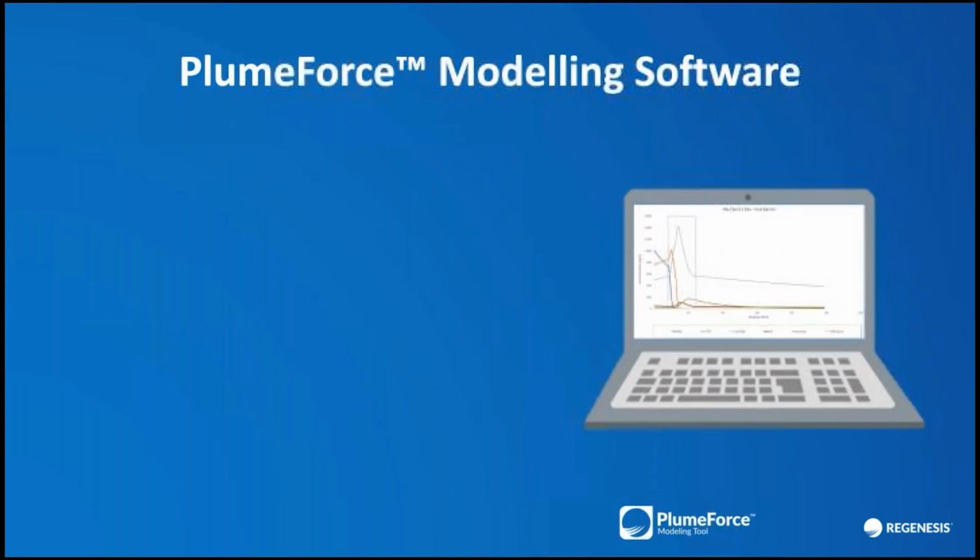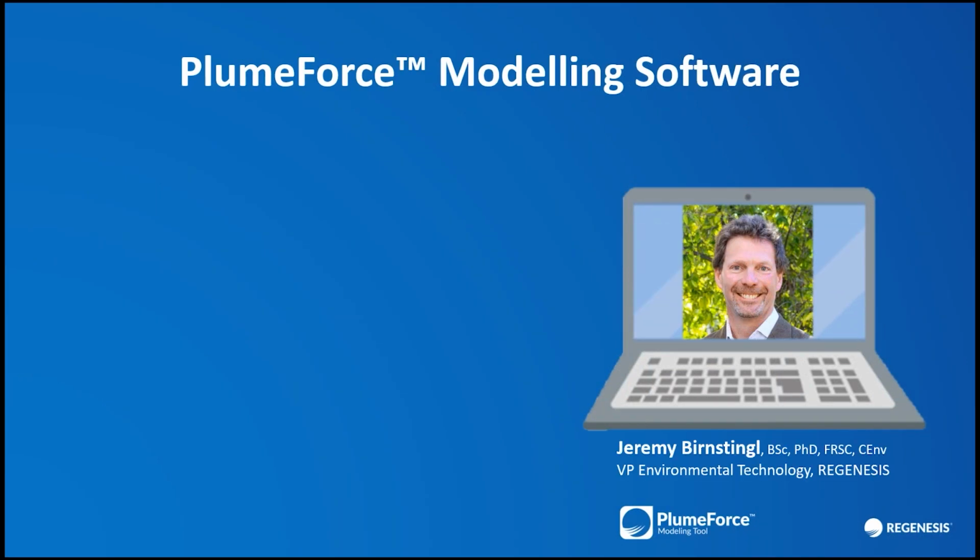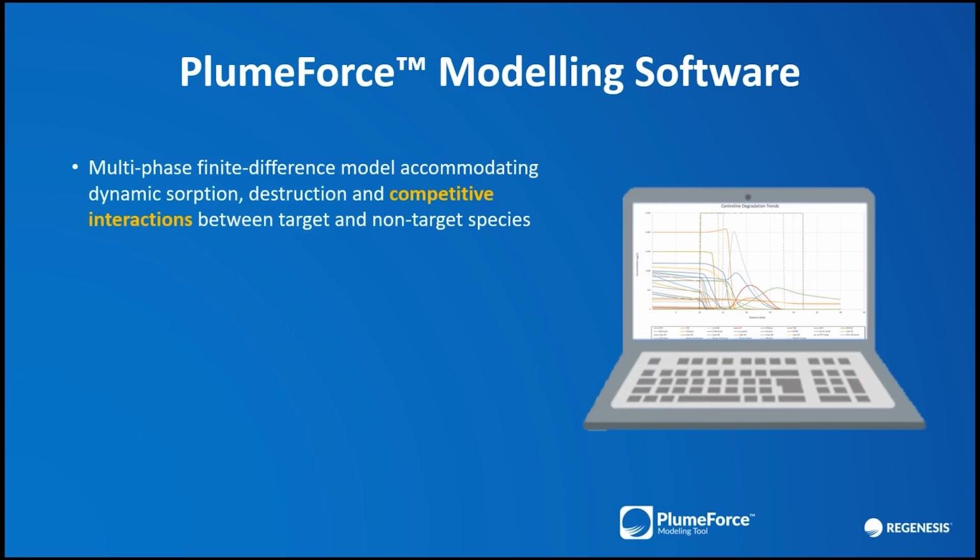PlumeForce is modeling software for in situ groundwater remediation. It was developed by REGENESIS, and we use it to support our clients' projects. It was designed by me starting in about 2016, when it became clear that existing off-the-shelf fate and transport models were limited in their ability to accommodate activated carbon and indeed other remediation projects in the calculations that they would do. PlumeForce is a multi-phase finite difference model that accommodates dynamic sorption, destruction, and competitive interactions between target species and between target and non-target species.